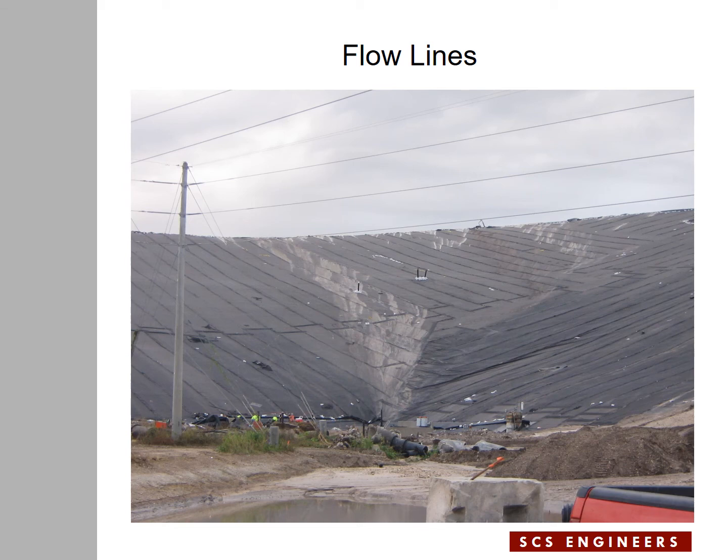The stain clearly shows the flow pattern of water in the concave surface area, in the pie area, and you can see that there's a lot of cross-panel flow in the pie-shaped area. When it comes to the bottom of the slope within the pie area, there's a concentrated flow reaching the bottom, which is that convergence of the water in the geocomposite.